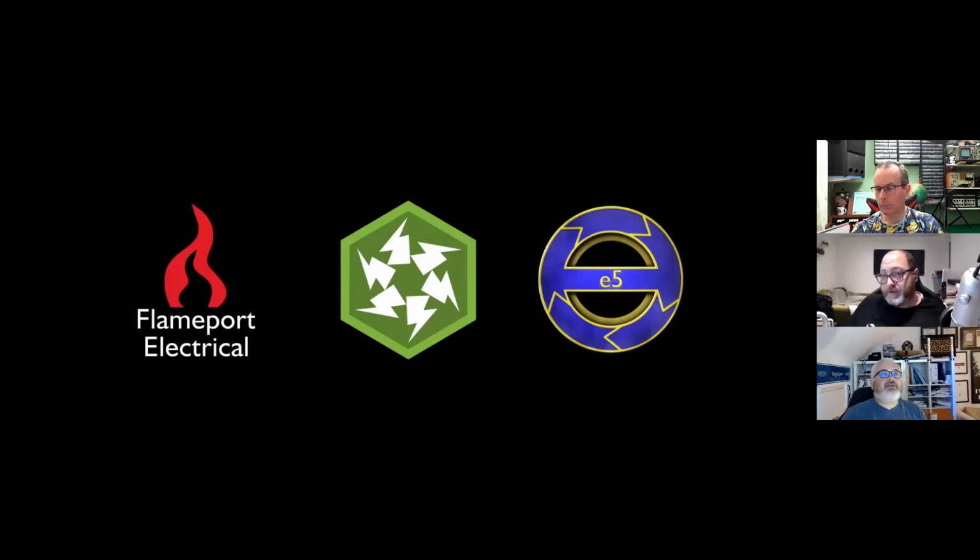So let me read something from BS 7430 out to you. Part 20, consumers' electrical installations. Two hazards may be present should an earth fault occur in an installation. Firstly, voltages appear between conductive parts. Yep, we know that. They constitute a shock hazard, funnily enough, termed indirect shock. We don't use that term anymore. We use basic and fault protection.